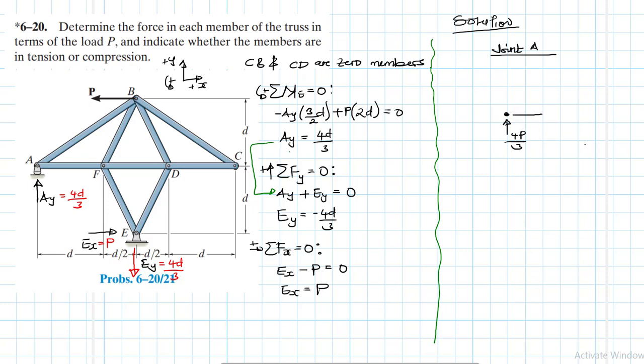Then let's assume in here we have a tension force. Looking at the convention, when you look at the way the forces are arranged, you expect a tension in AF. But even if there is no tension, the equations of equilibrium will correct the problem. Then we expect a compression in AB. And then we have this slope here. We didn't calculate the slopes, so let me indicate the slopes.